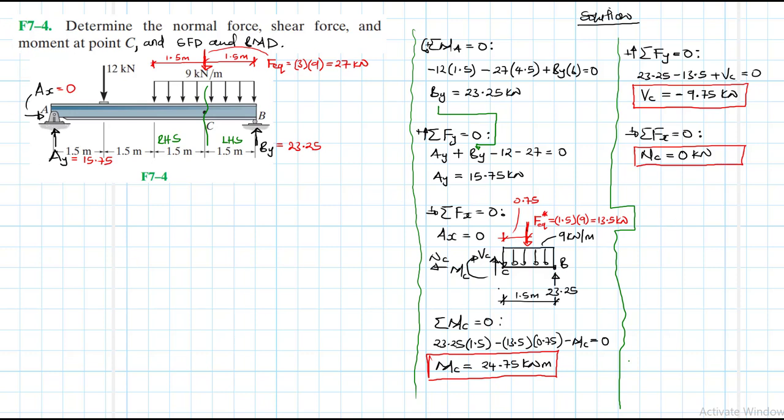So before we start drawing, I just remind you of something that you already know. You know that the rate of change of moment with respect to x gives us the shear force, and from the same equation, moment is therefore the area under the shear force diagram, right?